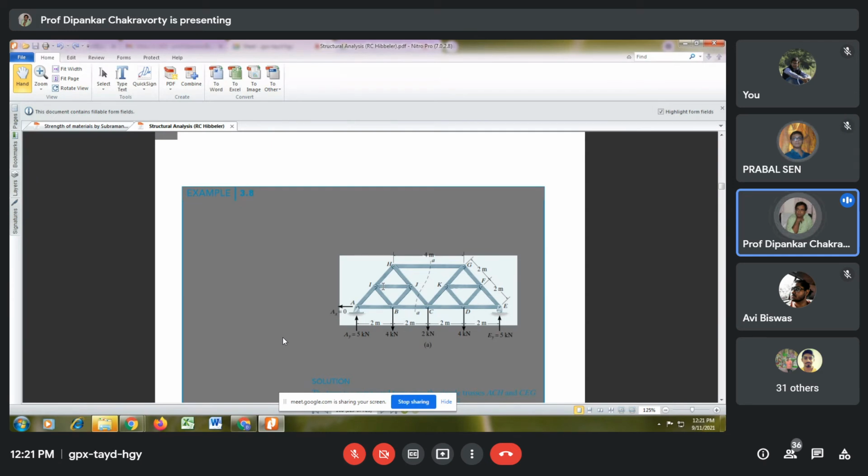Sir, please repeat. Surely I will repeat. I applied the method of joints at the support joint. In the method of joints, at any particular joint, two unknowns can be solved, and therefore I found that I cannot proceed. So I have taken a section. As I was telling a few minutes back, when I personally solve a truss, I go by a combined application of both method of joints and method of sections.